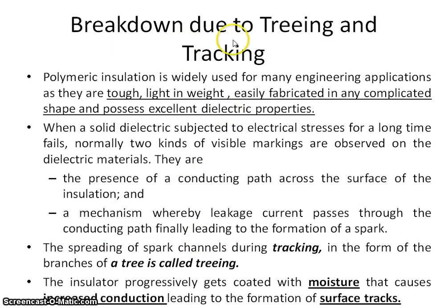Now, breakdown due to treeing and tracking. This is the most important breakdown because of the long operation of the insulating material. Polymeric insulation is widely used for many engineering applications. Why? Because this material is tough, light in weight, easily fabricated in any complicated shape, and possesses excellent dielectric properties.